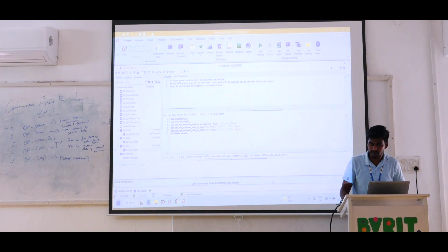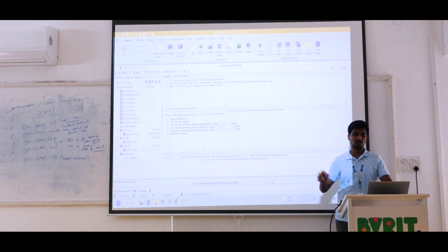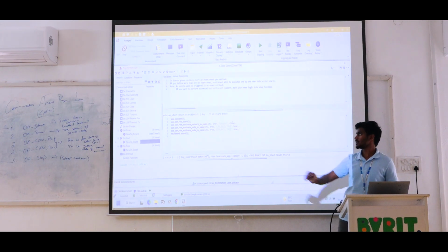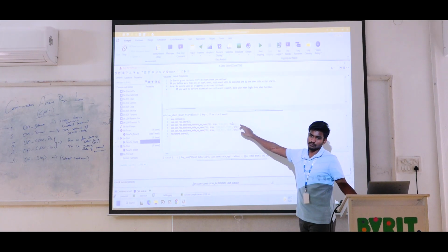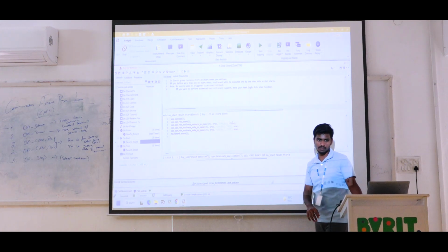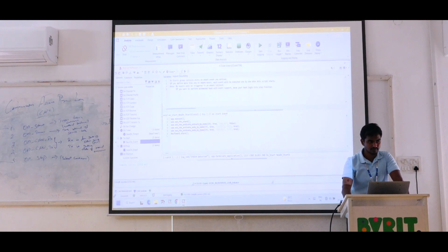Okay, so please check all the values are in false or not. So now you have to compile the code. Now you don't worry about whether it is on or off. You just run the script and go to the panel. That is enough. You made all of them false, but in the start network only we are giving the false, because we don't want to activate all the nodes. You just activate the network, but please activate only 2 nodes, TCU and then BCM. So compile and then start the scripting now.